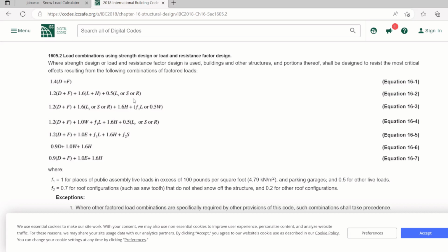So in Texas, for example, the snow load is only 5 PSF. So in the US, there are times that the roof snow load governs. But in the US, say Montana or probably Colorado or Idaho, it is interior and basically next to the border with Canada. So I assume the snow load there is really huge, or I would say bigger than the specified minimum roof snow load, which is 20 PSF.